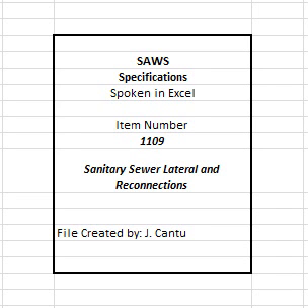3. Reconnection by excavation method. A. Remove a portion of existing sanitary sewer main or carrier pipe to expose the liner pipe. B. Provide sufficient working space for installing a prefabricated pipe saddle. C. Carefully cut the liner pipe, making a hole to accept the stub out protruding from the underside of the saddle. D. Strap on the saddle using a stainless steel band on each side of the saddle. Tighten the bands to produce a watertight seal of the saddle gasket to the liner pipe.